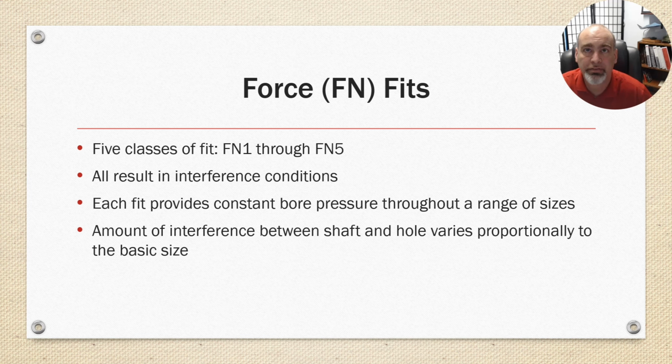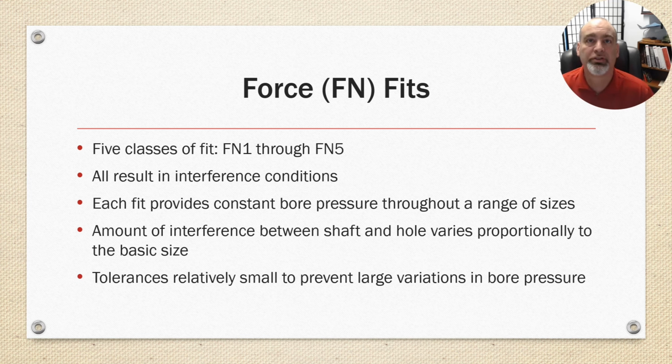The amount of interference between shaft and hole varies proportionally to the basic size, and tolerance is relatively small to prevent large variations in bore pressure. So very tight tolerances on these.